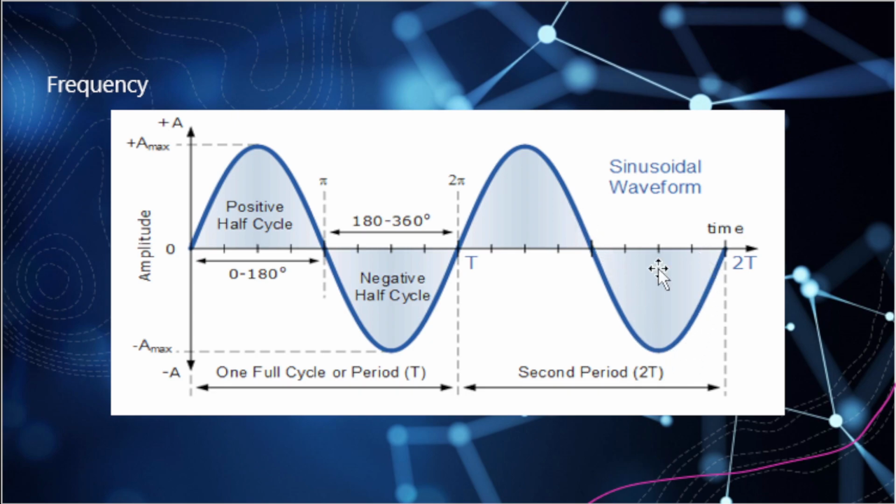Frequency measurements are often an essential part of preventative and corrective maintenance for communication and electronics equipment. Frequency measurements in the audio frequency range can be made by the comparison method or by a direct reading frequency meter. As you see in my office, often I use a frequency counter or my oscilloscope to make frequency measurements. Frequency comparisons can be made by the use of a calibrated audio frequency signal generator in conjunction with either an oscilloscope or a modulator and a zero-beat indicator device.